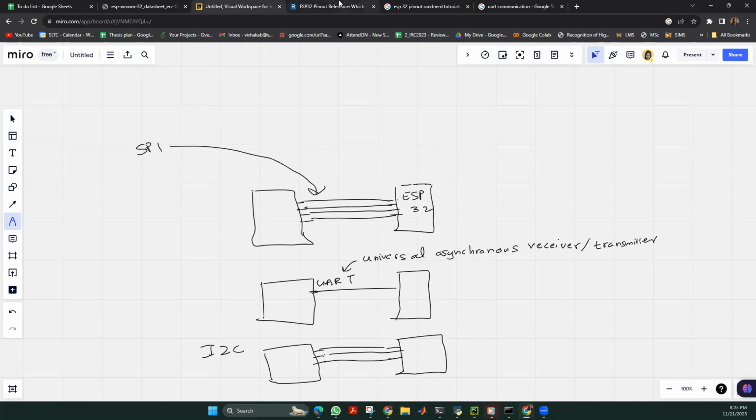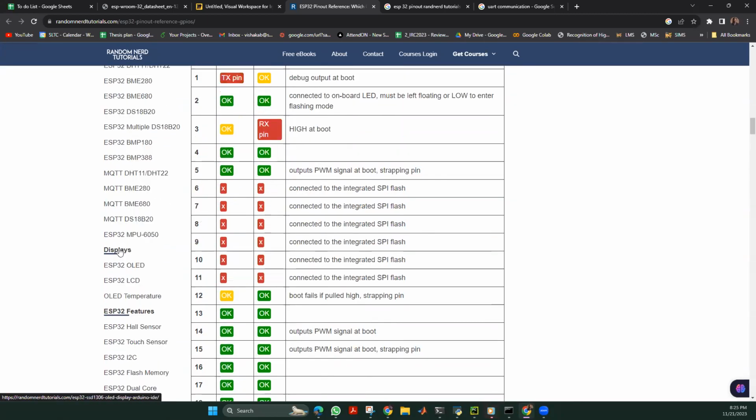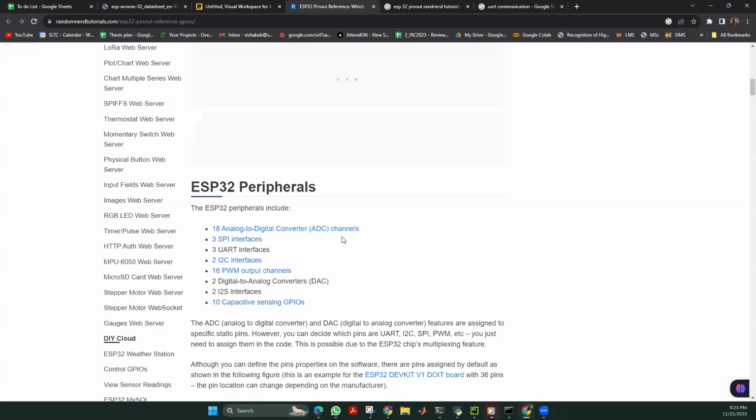So basically, when we take the overall summary, there are 18 ADC channels, or analog to digital converting channels. So you can input analog signals to these 18 channels or 18 pins. You can get a digital output from those inputs and work with digital information in the controller.